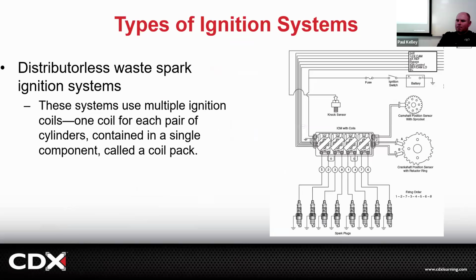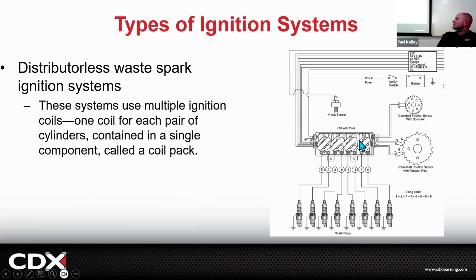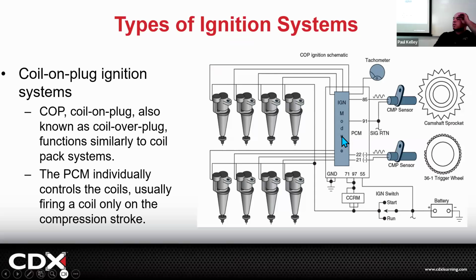It's just not mechanical like this. It's electrical, which means inside the ECM, there's going to be a switch, but it's not going to be a mechanical switch. They're going to use a transistor, which is going to pulse the ground, give the ground and take the ground away. So the ECM uses a transistor to do it, which I do show you here.